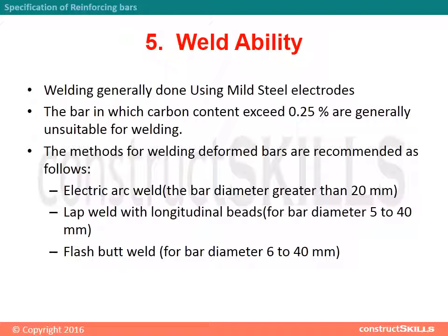Electric arc weld, lap weld with longitudinal beads, for bar diameter greater than 20 mm. Electric arc weld, for bar diameter 5 to 40 mm. Flash butt weld, for bar diameter 6 to 40 mm.